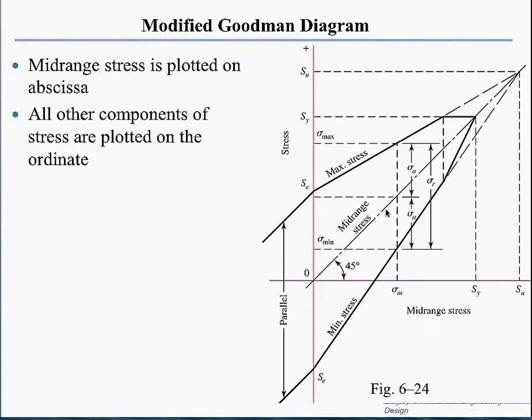And now if we add to that mean stress an alternating stress, so we add a plus alternating and a minus alternating, then we will produce two lines. One line that is the maximum, because the maximum is the mean plus the alternating, and the other line, not parallel to it, is the minimum, because this is the mean minus the alternating. Now these will go up to when the mean is 0, that's for fully reversed, and you can see here for fully reversed, the maximum is equal to the minimum but with a negative sign.